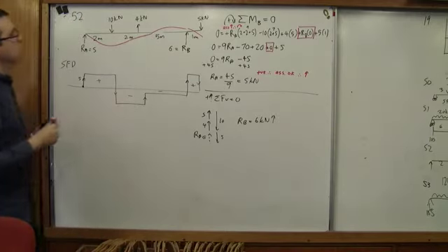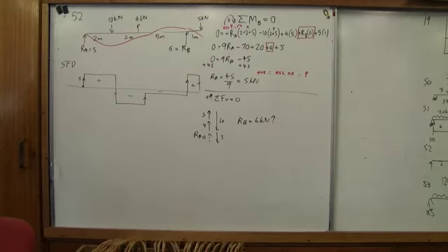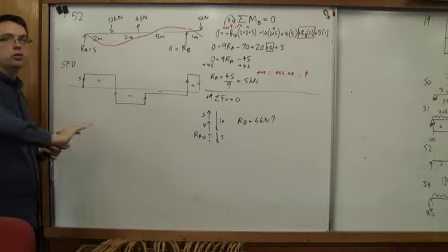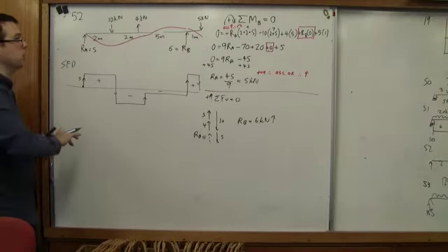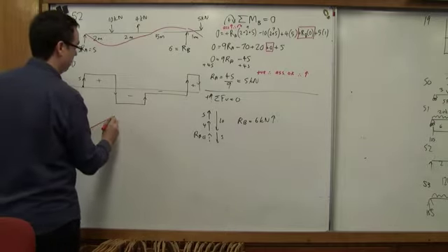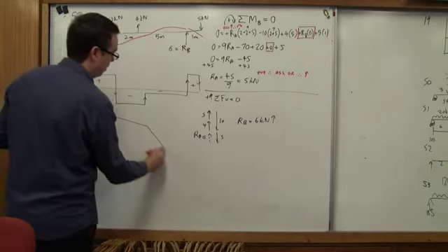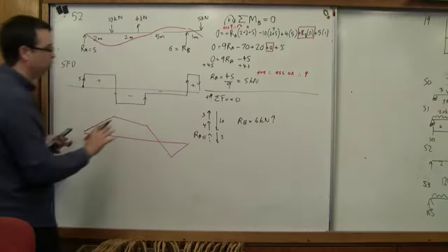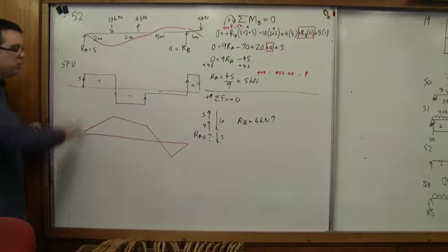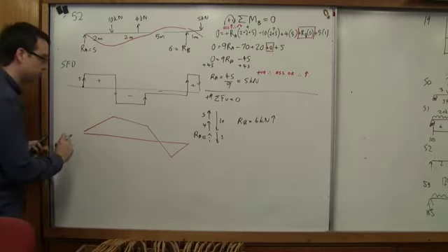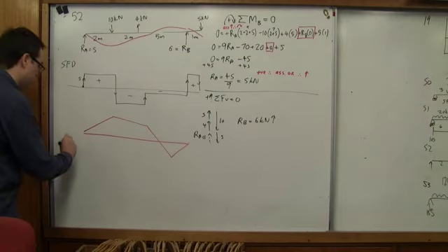Something along those lines. Now, some people draw their bending moment diagrams in that direction, but we can predict that our bending moment diagram, because it's not going to have any curves, because there's no uniformly distributed loads on this beam, it means that it's going to look something I would predict like this. I would predict it's going to look something in that ballpark. I don't know where that horizontal line is going to be. It might be steeper, it might be lower, but I'm going to predict it's going to look something like that. Let's have a look at what the answer looks like. The answer at this bookmark.